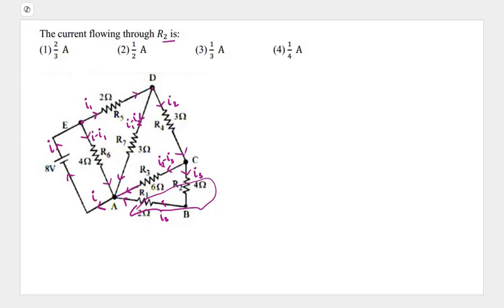Okay, so you can see how I can draw it. This is R5, this is R6, this is 3 ohms, this is R7, this is R3, then these two will become R1 and R2. Let us write R12 is 6 ohms and R3 is 6 ohms. Now notice this 6 ohms and this 6 ohms will be in parallel. When these two are in parallel, then 3 will come.